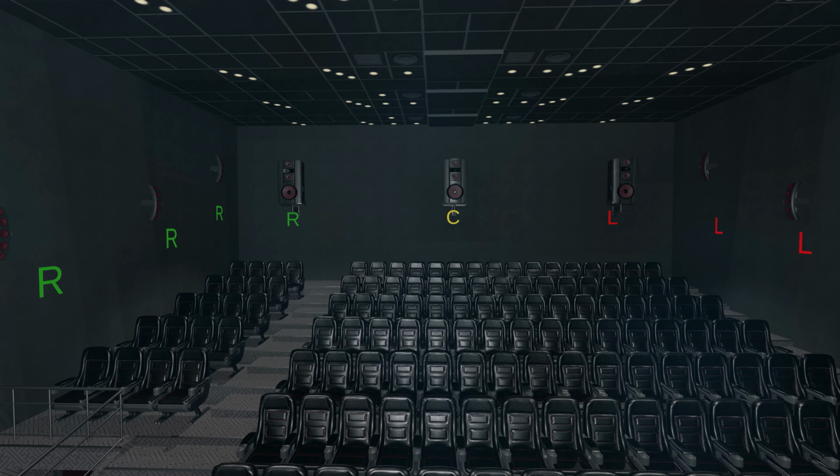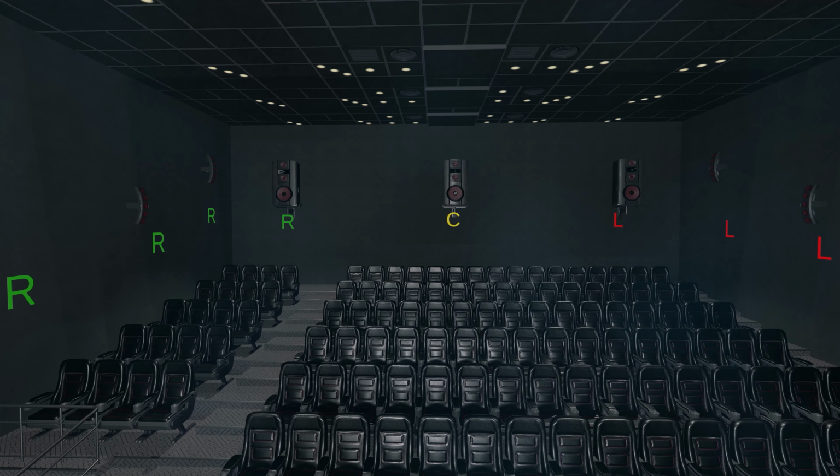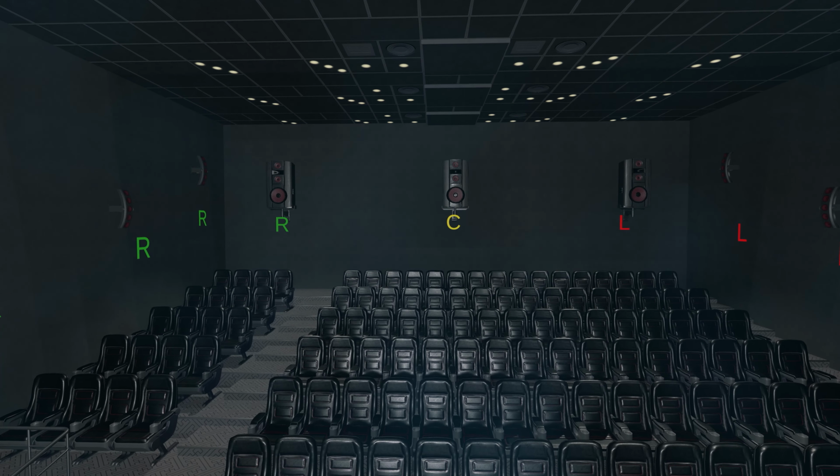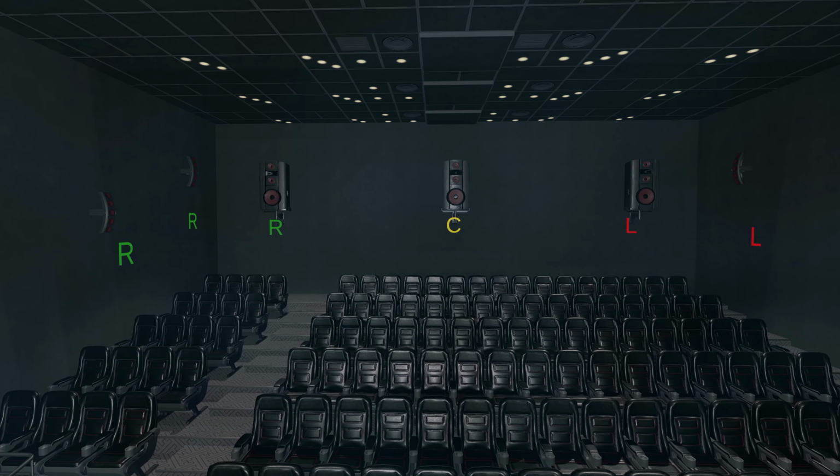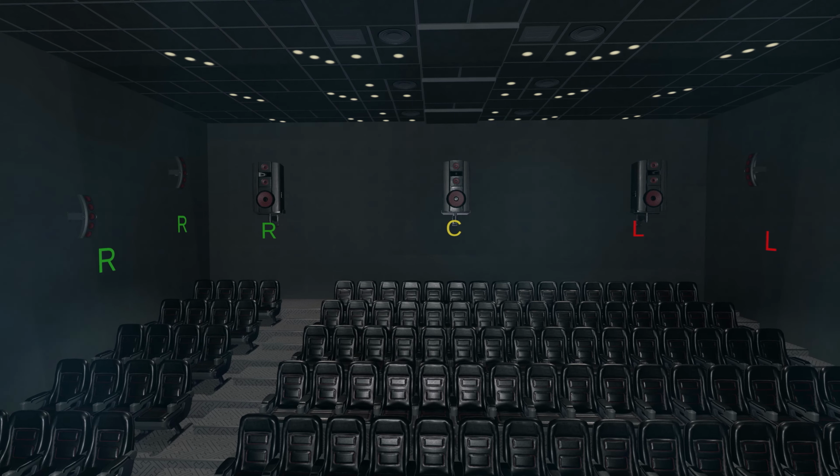However, for design considerations, the maximum sound pressure level that could be output by the sound system, for each individual speaker, should be equal to or greater than 105 dB without amplifiers overloading or clipping.